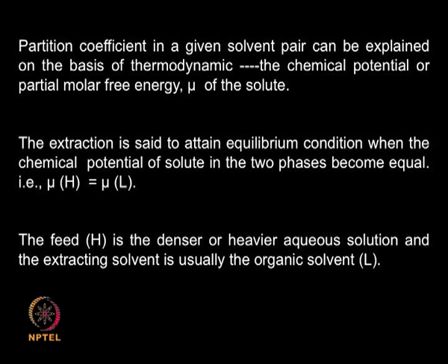That is an ideal condition, but generally sometimes we do not give enough time for the solute to partition effectively and reach an equilibrium. If the viscosities are very large, then the movement of the solute molecules from the heavy phase to the light phase takes a longer time, but I might not wait for such a long time. So they actually do not reach an equilibrium. But for design purposes or calculation purposes, we can assume that the chemical potentials of the streams leaving the extractor reach an equilibrium, that means they are equal.